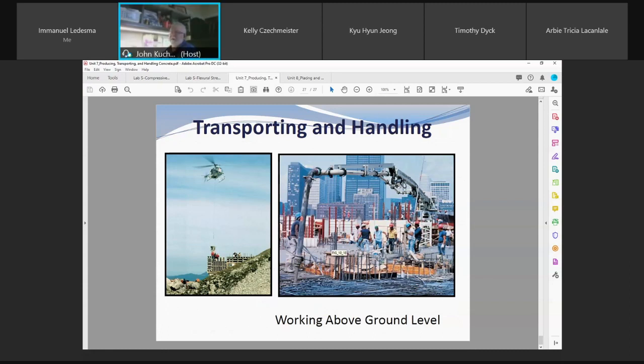The Burj Khalifa in Dubai, most of that concrete I think was pumped. You can pump concrete phenomenal distances if you have a pump mix. The mix design that we did in our lab, you would never use that as a pump mix. Okay? You can have a 30 MPa mix for slabs, a 30 MPa mix for columns, a 30 MPa mix for grade beams, and a 30 MPa mix that you want to pump. They're all different proportions. You're not only going to have one mix for everything.